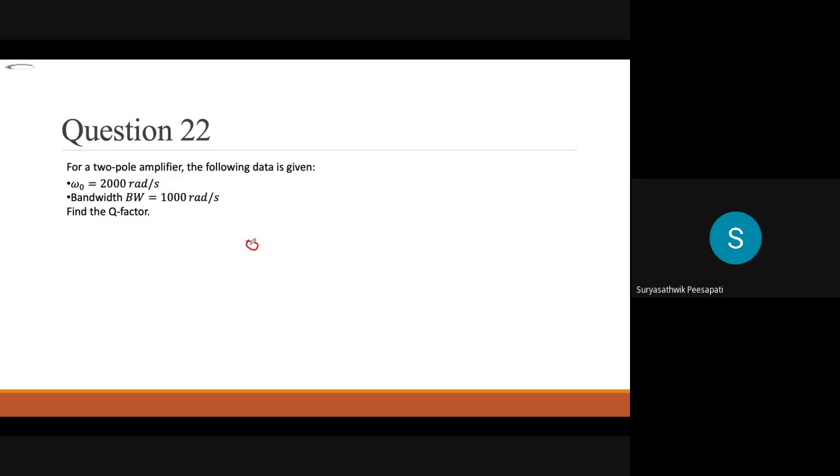Omega naught by bandwidth, ma'am. Yes, omega naught by bandwidth. Rad per second, and this is 1000. So the Q factor is 2.